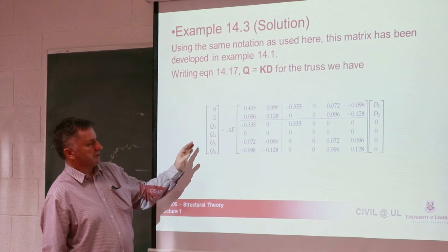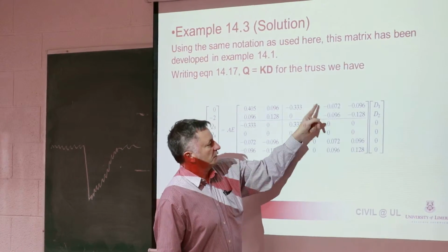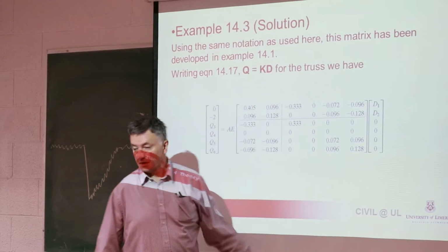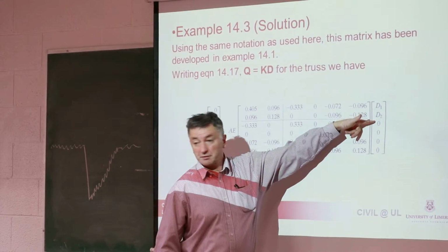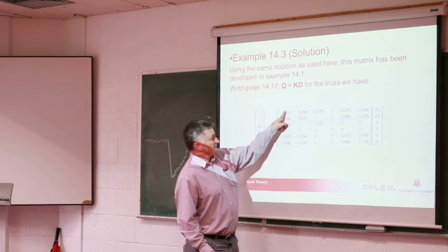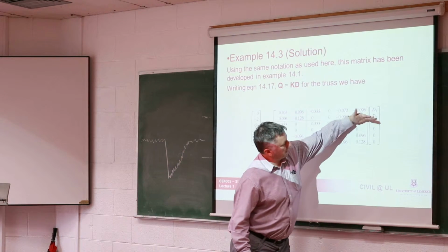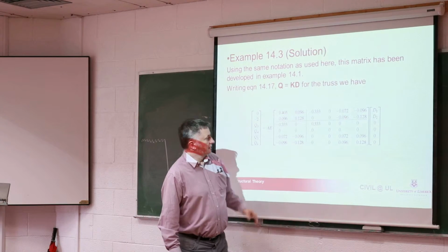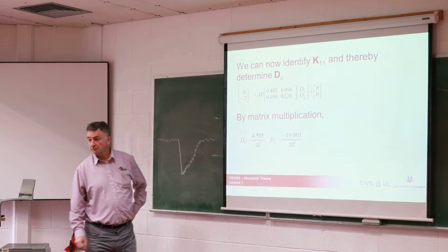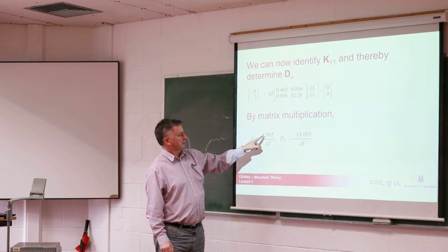You split the equation, and if you look at it, you'll see that all of these coefficients are going to end up getting multiplied by 0, by 0, by 0, and by 0, yeah? Those 4 columns will multiply by those 4 rows in accordance with normal matrix multiplication. Therefore, you can see this is the only business end in the top 2 equations. All of that multiplied by all of that goes to 0. So that top set of equations reduces to that, yeah? Which enables us to solve for the 2 unknown displacements, and we have them here.